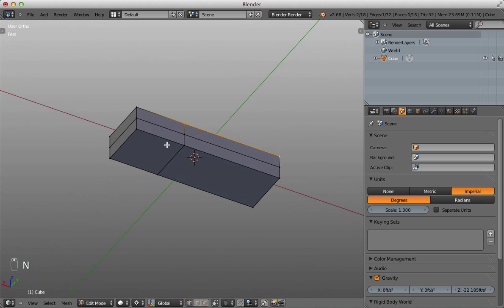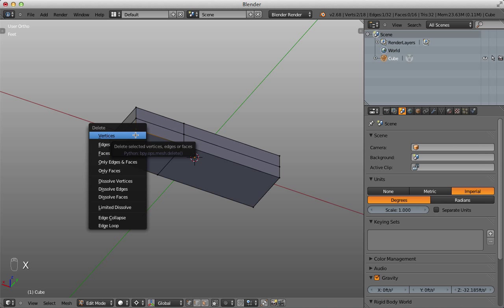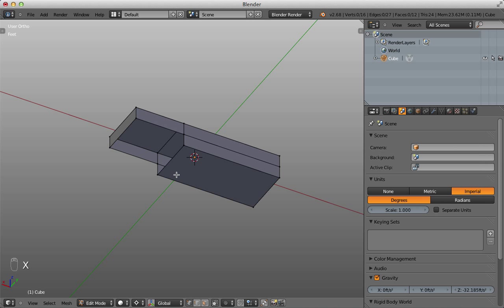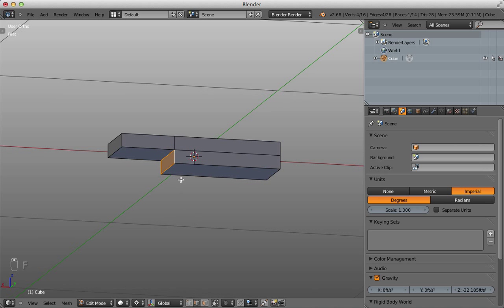So at this point, I can go ahead, maybe from below, select those points and delete them. Press X, select vertices, and then I can select those points, press F, and I selected all vertices. I can also select opposite edges, press F. It's all doing the same.